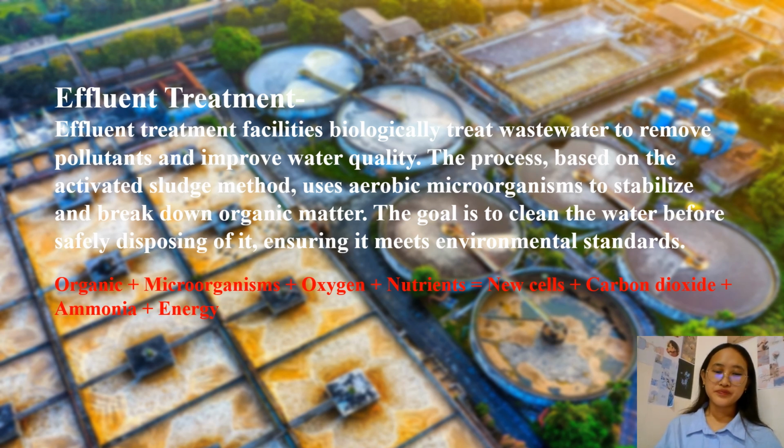So this treatment provides removal of major pollutants from the effluent, right? So this also involves the stabilization of organic molecules by excess of microorganisms. Okay, so we can depict that as an equation, right? So the equation was organic molecule plus microorganisms plus oxygen plus nutrient, which gives new cells plus ammonia, carbon dioxide, and energy as well.